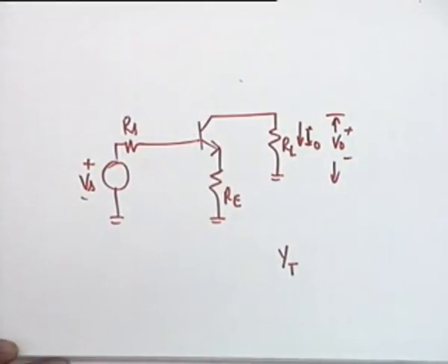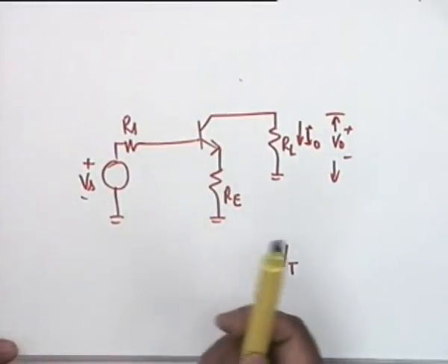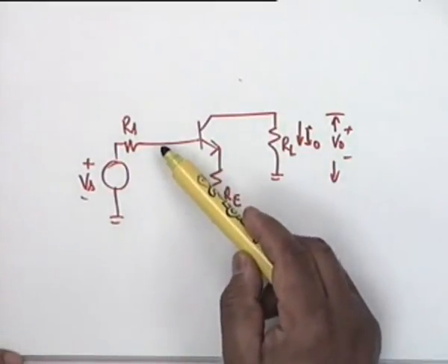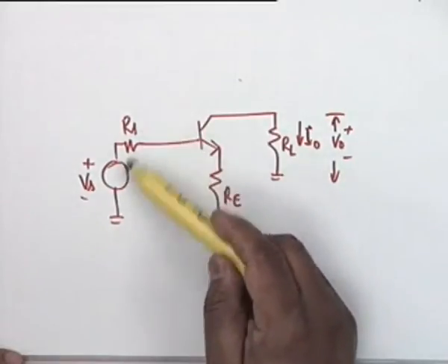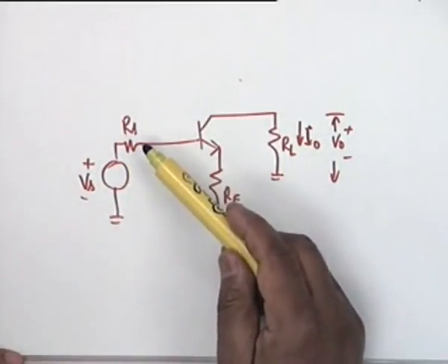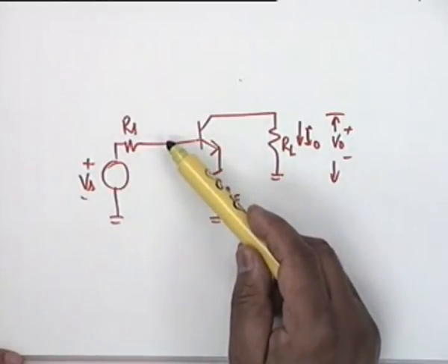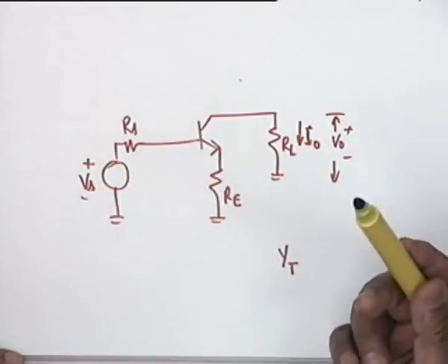Now, in order to draw the equivalent circuit, since it is possible to take account of Rx, let's do that. Rx would be in series, and there is one more reason to consider Rs: if this is an ideal or nearly ideal voltage source, the source resistance would be comparable to Rx, and since it is easy to take account of this, we do that.